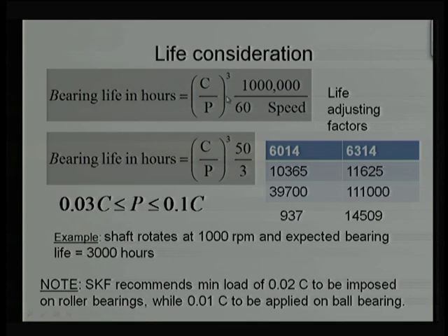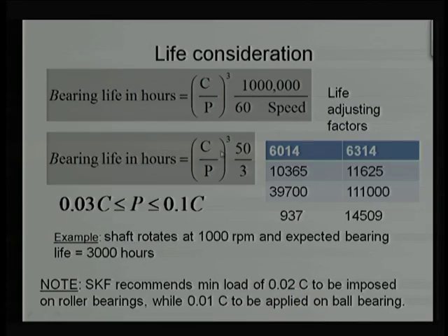Similarly, we are assuming there is ideal lubrication. Wherever lubrication is required, that is getting supplied or fulfilled completely. But there is a possibility of starvation, and there is a possibility of excess lubrication that has not been counted over here. So there will be some factor counted over here. Another thing is that we are assuming the bearing material is perfect.